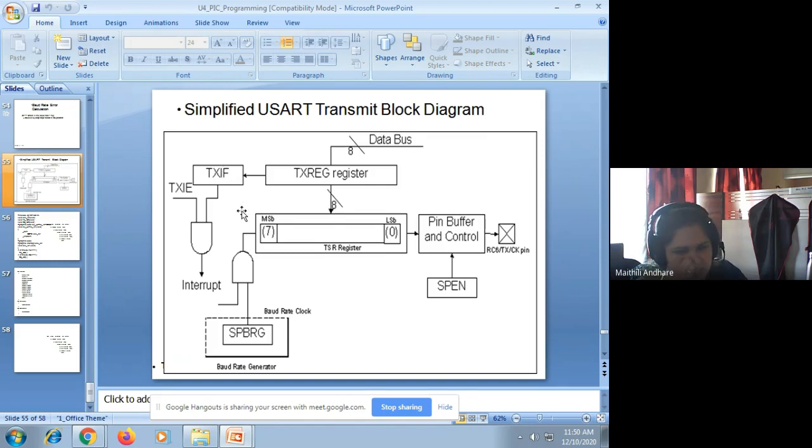The priority bit is very rarely required because only if a number of things are happening at the same time could we think of the priority. Otherwise, that bit is only available wherever you require, you can use that bit. But these are the two important bits related to the interrupt: flag bit and enable bit. That's it.